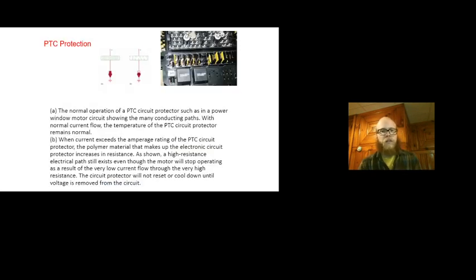On some vehicles, though, especially ones where maybe a computer is what's actually rolling the window up, sometimes that switch is just sending a voltage signal to a computer in the door or under the dashboard, showing a request, and then the computer rolls the windows up. Think about one touch up or one touch down, right? You pull all the way up on the switch and the window magically rolls all the way to the top. When it gets to the top, the computer's usually pretty good about stopping or cutting off the current flow right off the bat.